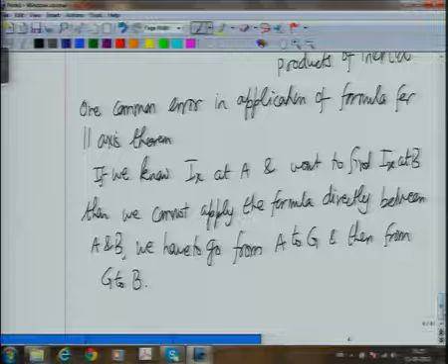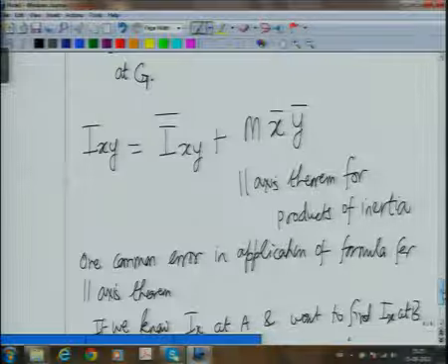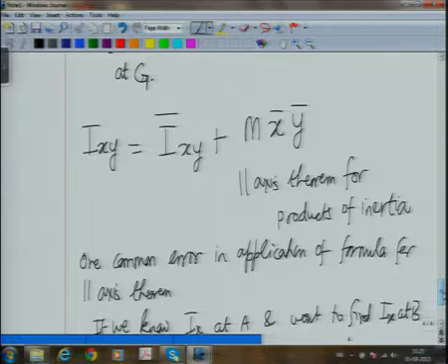Okay. Now, one more thing, maybe in product of inertia. So you see what you are talking of is one point, centroidal axis, and another point. Now in this formula you have m times x bar y bar. Suppose your point A and G are located in such a way that you are shifting only along one axis, let us say only along x. Then what will happen in the product of inertia formula?